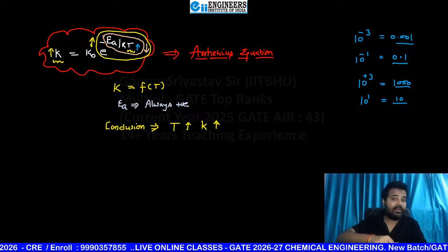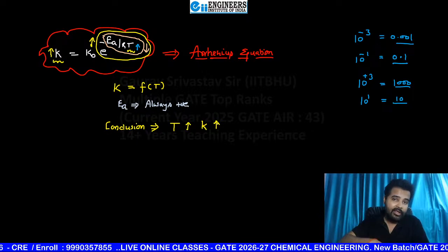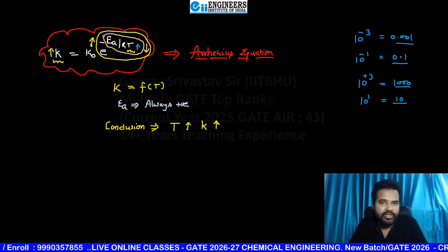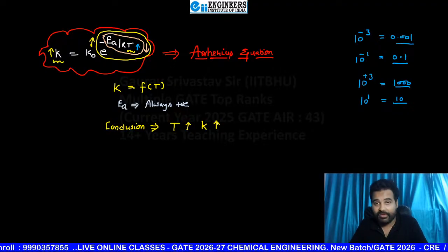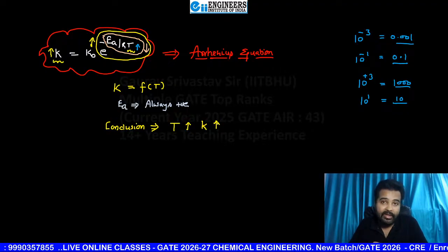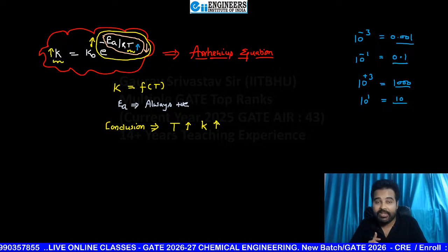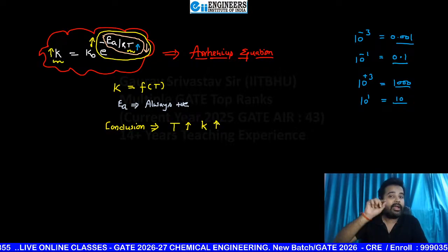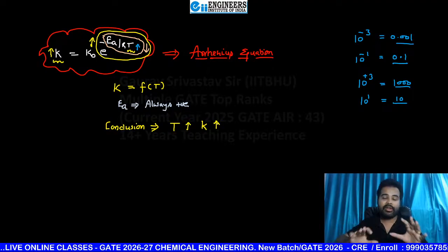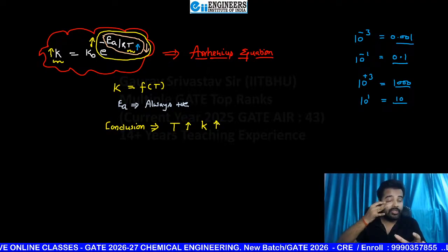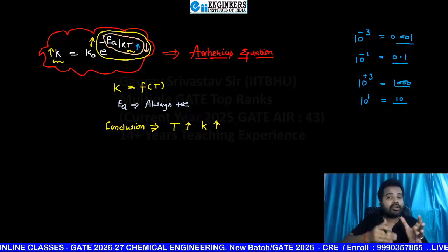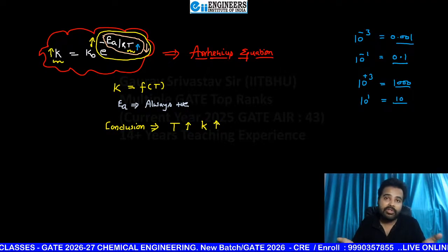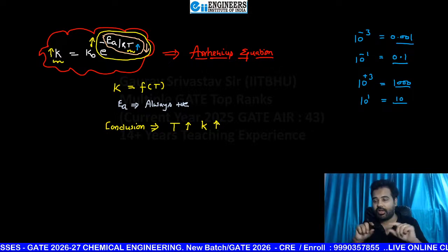But if it is not irreversible, if it is reversible, then for reversible exothermic, definitely the favorable condition is low temperature. Just as you saw in the conclusion, Ke is going to decrease when you increase temperature for a reversible exothermic reaction. For a reversible exothermic reaction, when you increase temperature, Ke decreases, and when Ke decreases, conversion also decreases. The equilibrium conversion you get is not 100%.